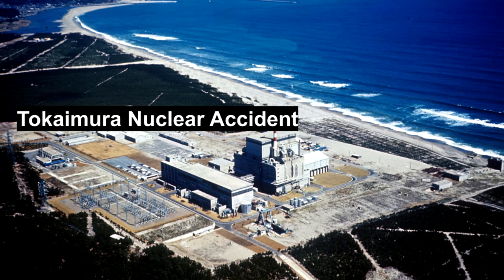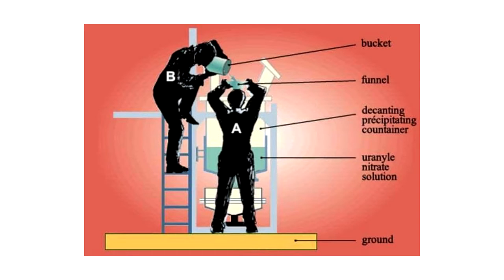Another very major but small nuclear accident was the Tokaimura nuclear accident in Ibaraki Prefecture, Japan. At approximately 10:35 a.m. on September 30th, 1999, workers at the JCO nuclear fuel processing plant poured a 7th batch of 18.8% enriched uranyl nitrate solution along with uranium-235 into a precipitation vessel. The goal of this process is to convert the isotopically enriched uranium hexafluoride into uranium dioxide fuel.